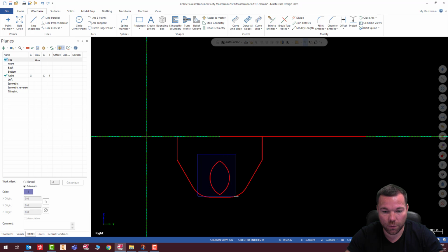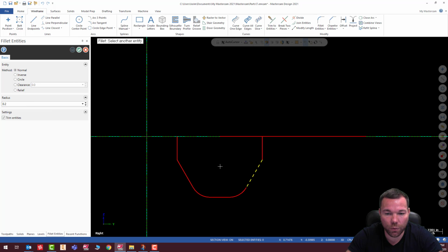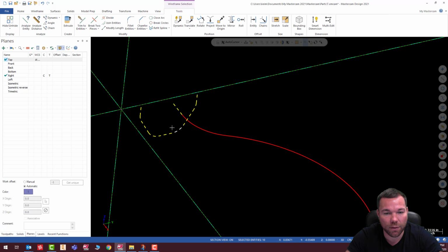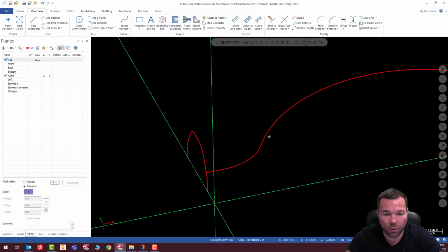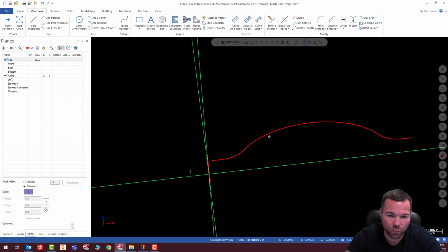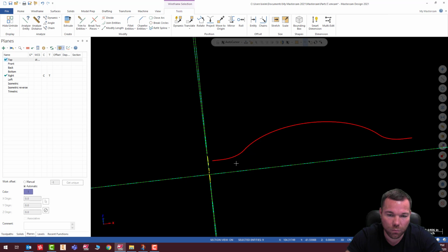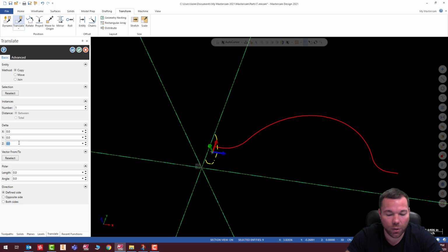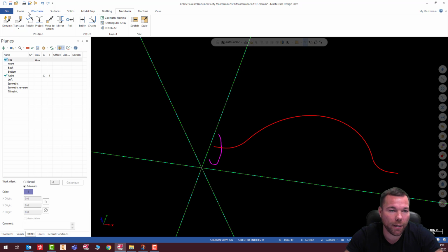So trim all that stuff. Get rid of that. And we've got to put our radii on, 0.2. There. Check. Okay, now the only thing I need to do is translate this and bring it forward that 1/8 inch. Let me grab it here. There we go, got everything, so let's transform that. Translate Z 0.125, and let's move that, check. Okay. I could have drawn it there. I just forgot to change this, so no big deal.